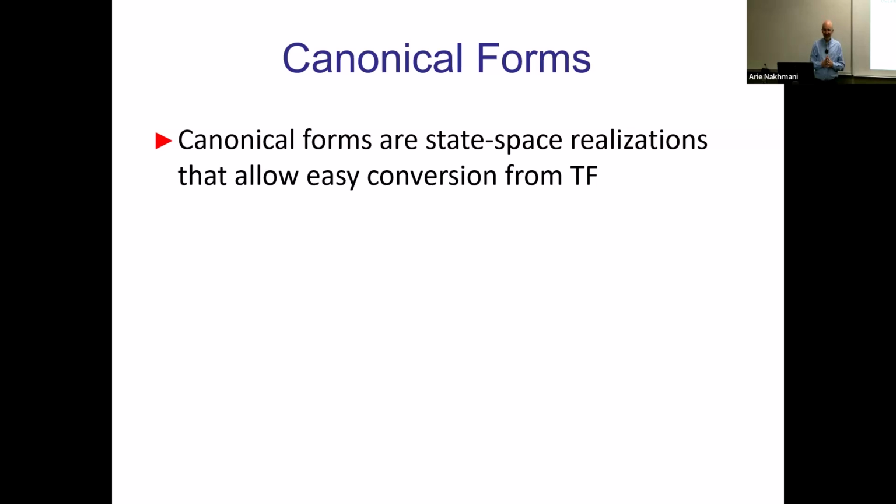All right. So here's how we do that. There are multiple canonical forms which represent particular types of transfer functions. They include controller form, observer form, diagonal form. You can use any of them. All of them are equivalent, giving you exactly the same transfer function. And they obviously have a similarity transform between them if they are controllable and observable. So it's very easy to do.